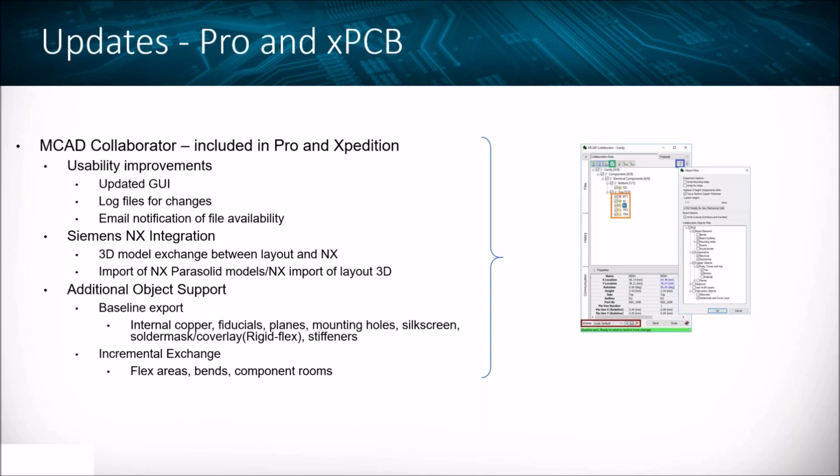So essentially, we send a baseline from the mechanical tool to an electrical tool, and we are able to import that baseline, such as a board outline, and implement it directly in the layout tool. Okay, so it allows us to interface much more directly with mechanical engineers. It works with SolidWorks, Pro-E, NX, anything that supports the ProStep format or IDX file type.